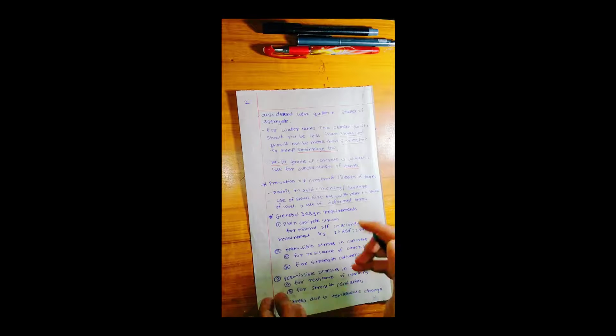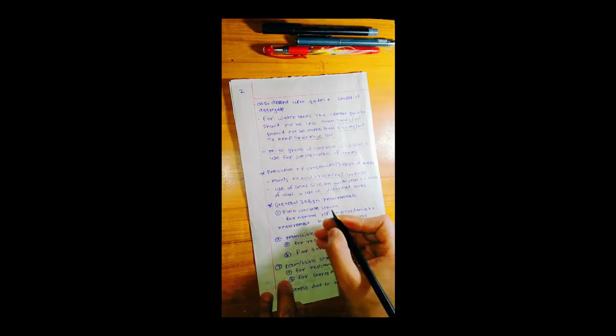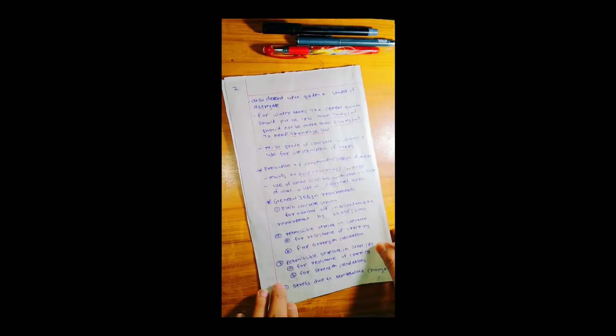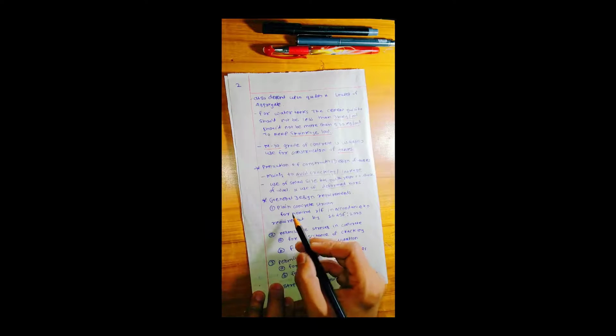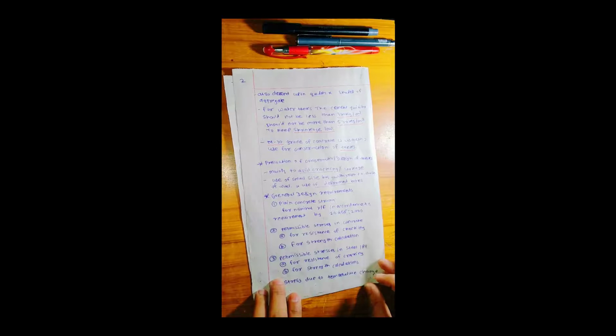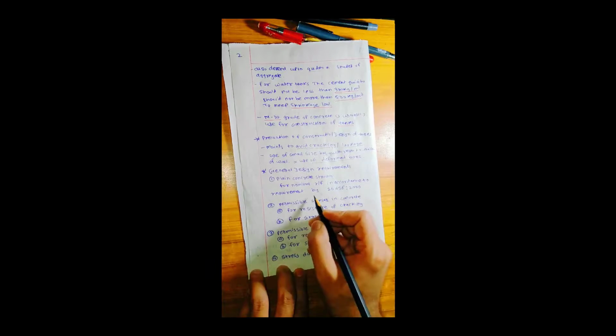These deformed bars are generally used as our regular tensile steel bars. Due to these bars, while using them in a water tank, the bonding between concrete and steel will be good. General considerations of requirements during design of a water tank. First, plain concrete design, with nominal reinforcement according to IS 456.